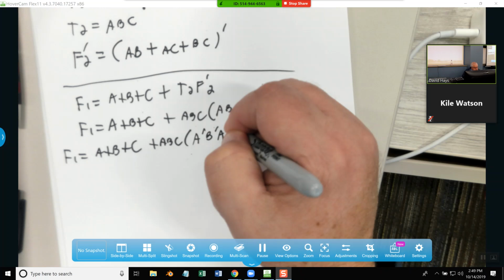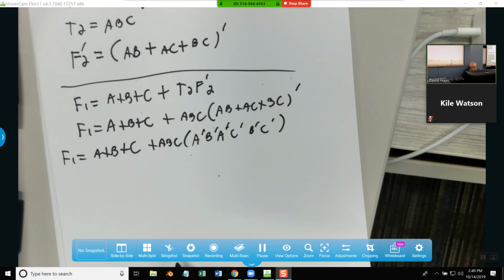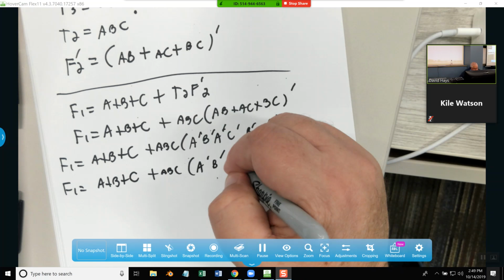Okay, our design procedure. The design of combinational circuits starts from a specification of design objectives, culminates in a logic circuit diagram, or a set of Boolean functions from which logic diagram can be obtained. And you'll see these following steps. From the specification of circuit, determine the required number of inputs and outputs and assign a symbol to each. Derive the truth table and define the required relationship between the inputs and outputs. Obtain the simplified Boolean expression function for each output as a function of the input variables. And draw the logic diagram, verify the correctness design manually or by simulation.